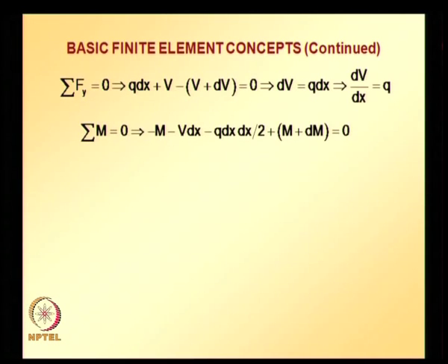The sum of all forces in the y direction equal to 0 gives us that the spatial derivative of shear force is equal to the distributed load applied, and the sum of moments equal to 0 gives us that equation.